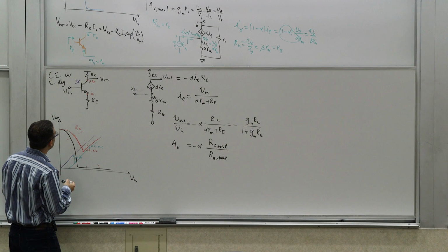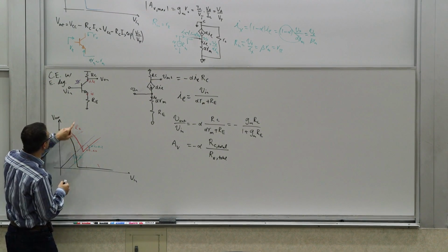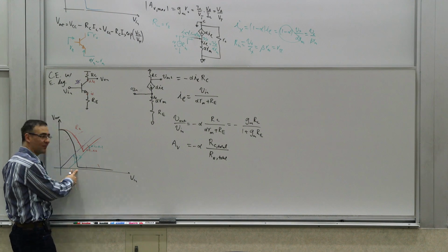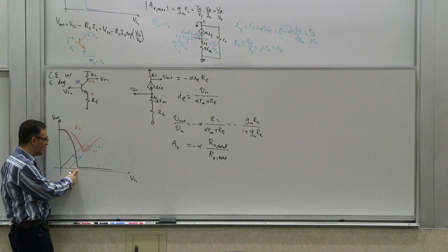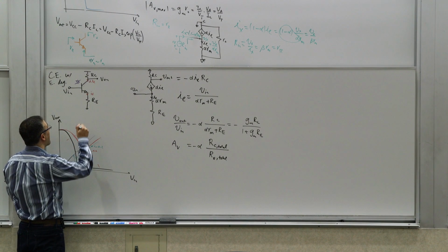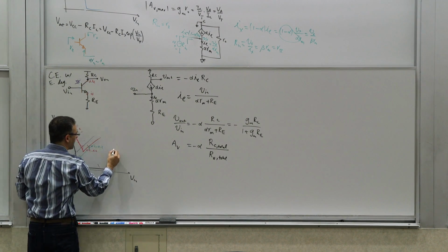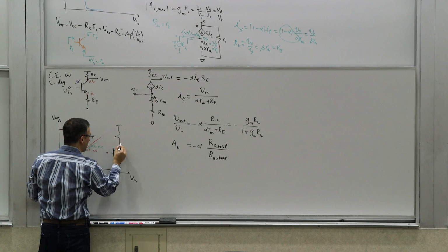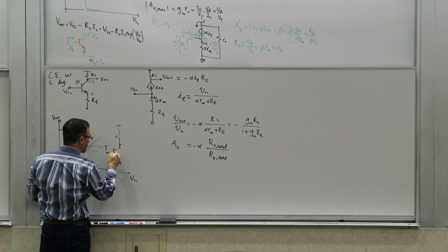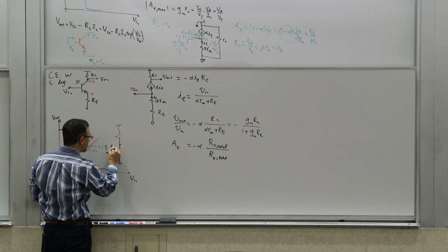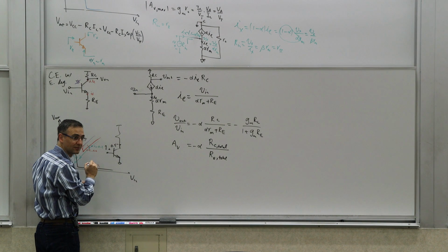Well, the diode argument doesn't apply because this voltage, as it goes, happens over a short period of time anyway. So it does apply, but when it applies, essentially you're here. You've already made it here. Because for that to happen, if there is no emitter degeneration and this voltage is going up, for this to get below that one, it has to be around 0.5 or 0.6 volts below this, right?